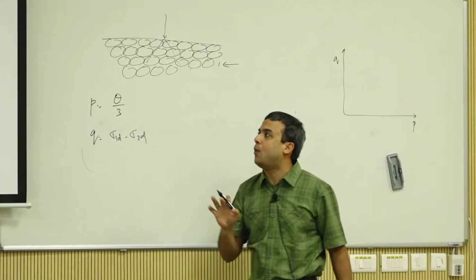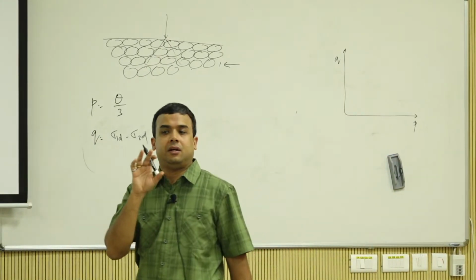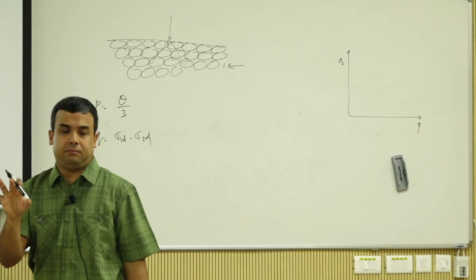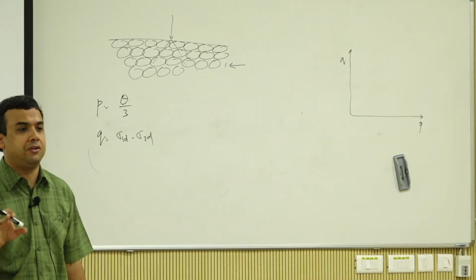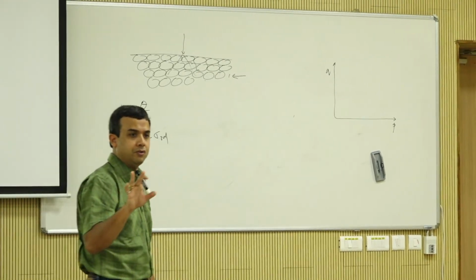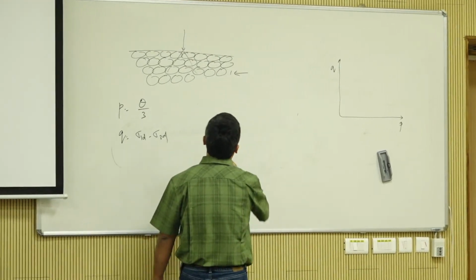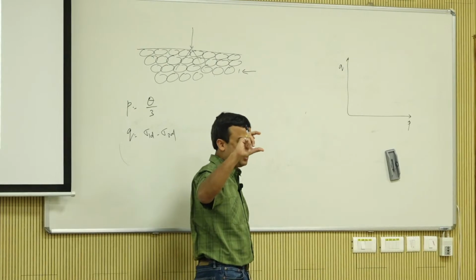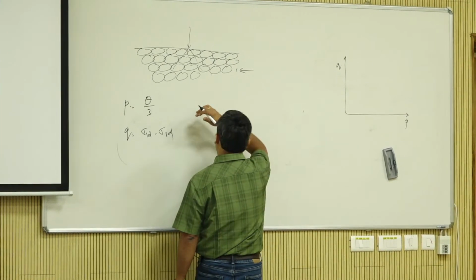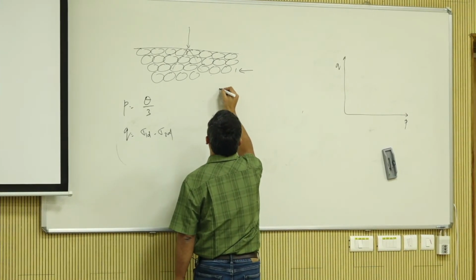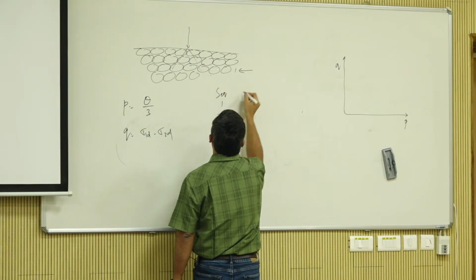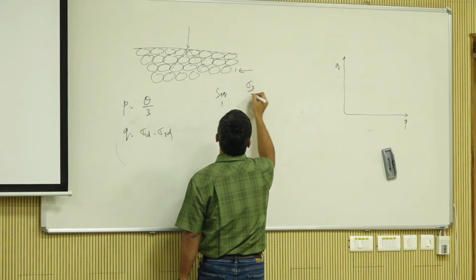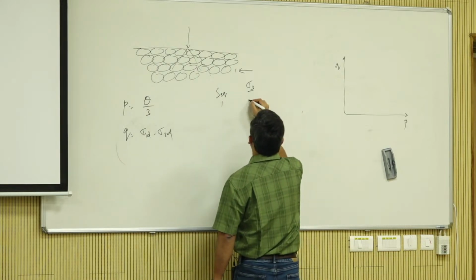Let us take our traditional resilient modulus test. I'm going to just work on the first pulse group, or first sequence. So for sequence number 1, your sigma 3 is what? Who remembers? 3 psi.